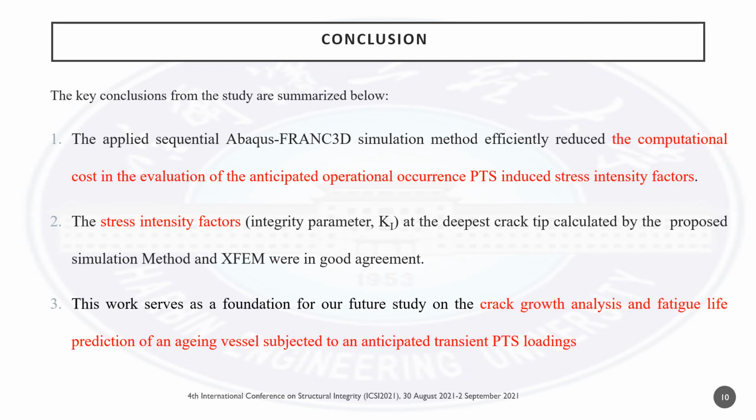In conclusion, the applied sequential Abaqus-FRANC3D simulation method efficiently reduced the computational cost in evaluating the anticipated operational occurrence, PTS, induced stress intensity factors. Also, the stress intensity factors determined at the deepest crack tip based on our simulation method were in good agreement with the extended finite element method.